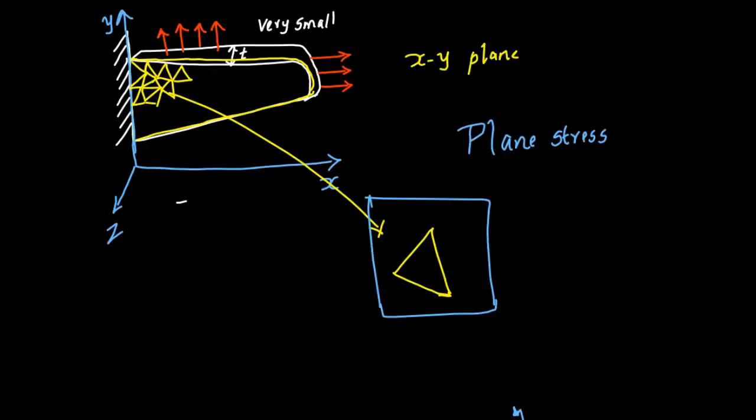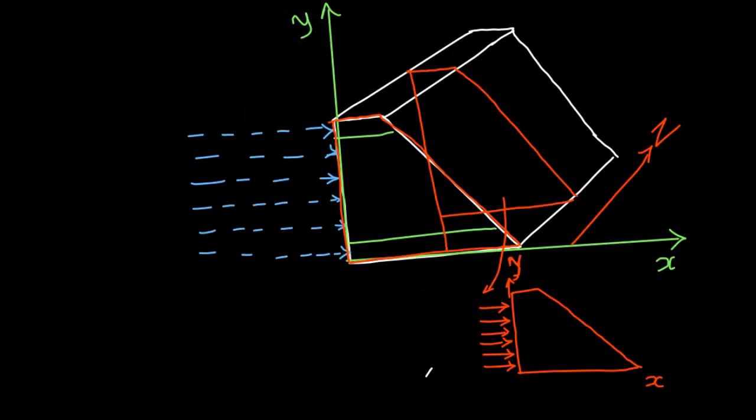In the previous case, the dimension along the z direction is very small compared to the other two dimensions. Here, the dimension along the z direction is highly pronounced. So the strain produced along the z direction is going to be infinitesimally small. For all practicable purposes, we are going to ignore the strain along the z direction without incurring any serious error in mathematics. This condition is called the plane strain condition.